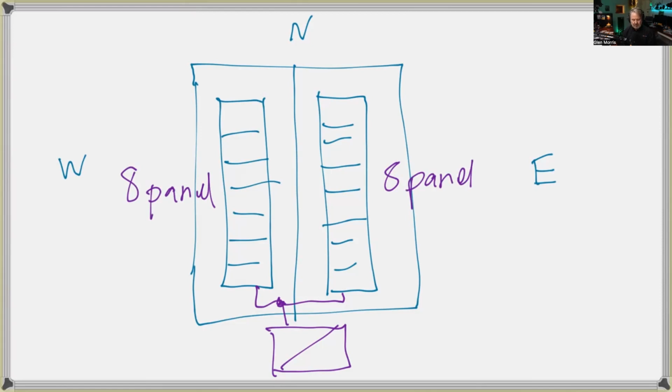You might think, surely it's better to have two separately controlled arrays with two separate trackers. Surely it's going to produce more energy. But it turns out if there's no shading on either roof, it doesn't make any difference in practice. This has been proven by Fronius and SMA with test rigs, showing there's almost no difference. But it's really about that shading.